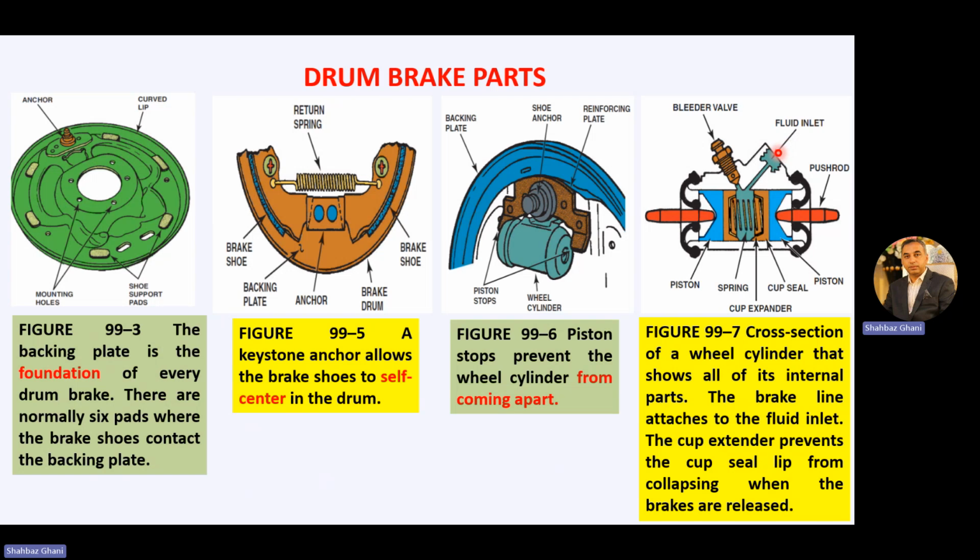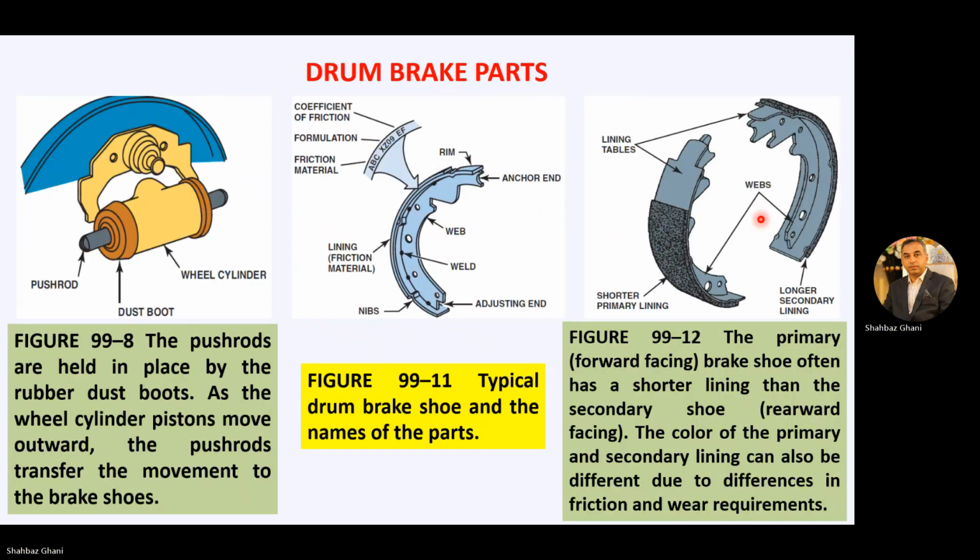When we press the pedal, the brake fluid comes with the pressure, the spring is there, and it forces the piston outward, the push rod goes out, and it energizes the shoes. When you release the foot pedal, the hydraulic pressure drops and the return spring closes and the piston comes back to its original position.